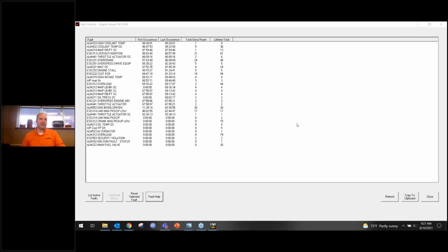Well, guess what our trusting customer decided to do? They decided that they were going to disconnect the detonation sensors. So what started as really a cooling issue, they've now turned into a detonation issue. Well, when they disconnect the detonation sensors, we don't have that feedback loop. So the detonation sensor allows us to kind of run right up to the edge.